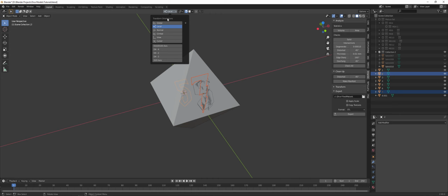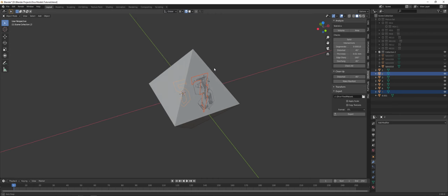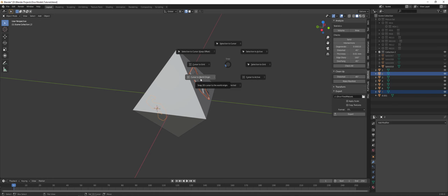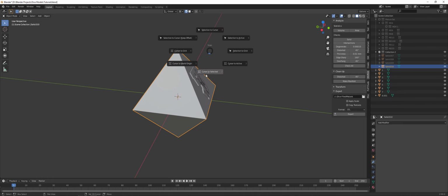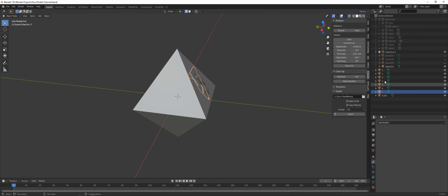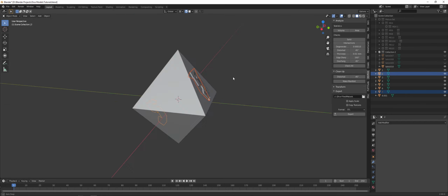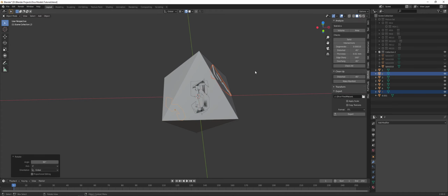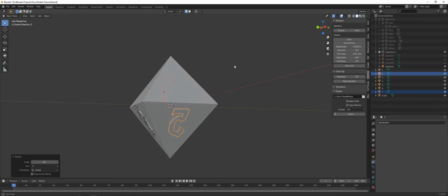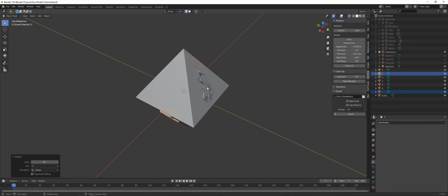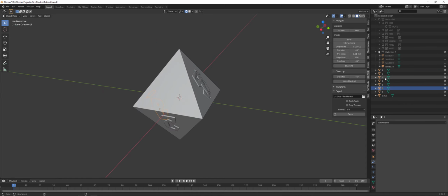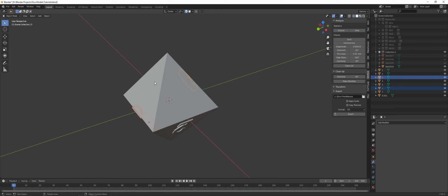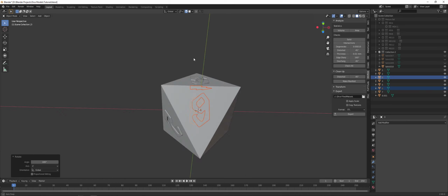You're going to go to global coordinates, 3D cursor. Make sure that your 3D cursor is at the world origin or at the center of your dice if it's different. And then you grab your 2 numbers, rotate Z 90 degrees. Now, you can actually do this much easier without a 3D cursor. Just change the median point because the center is also going to be the median point between the 2 numbers, right? So you grab the 6 and 3, which should be on the opposite side. You move them around the z-axis 180 degrees, and you have them placed.